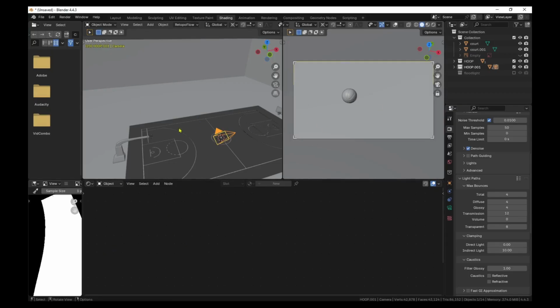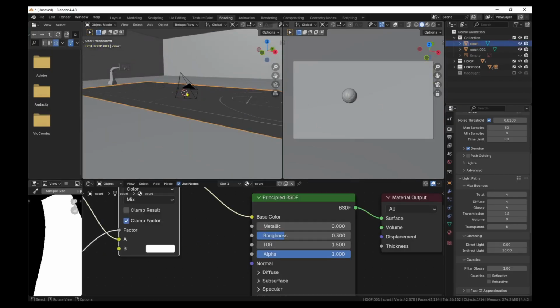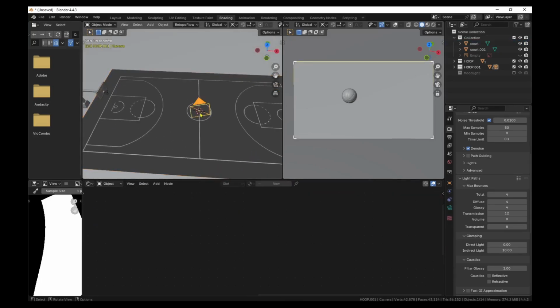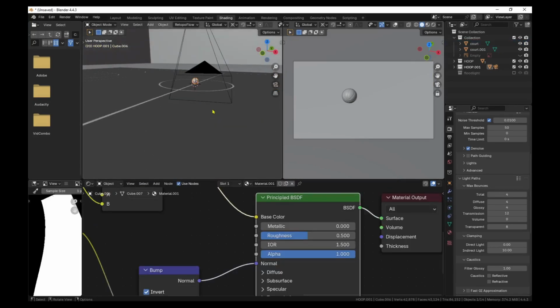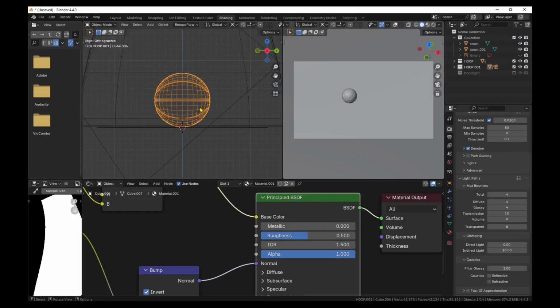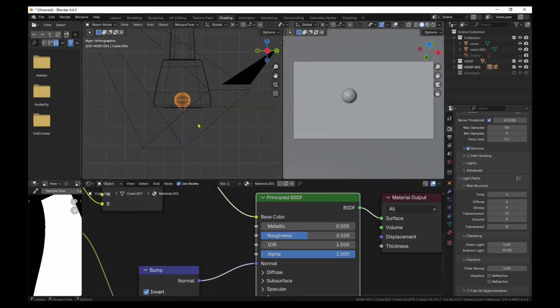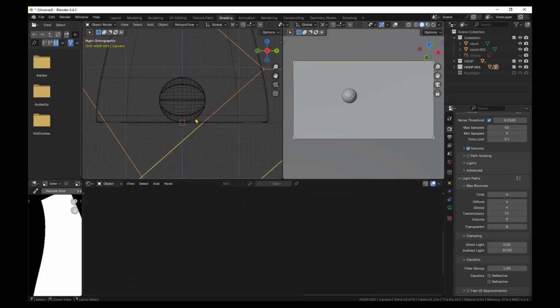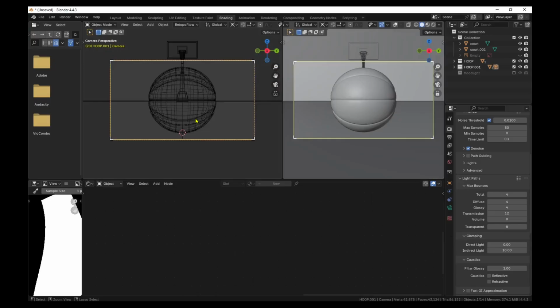So now we want to light only the ball. So let's bring our focus to the basketball. Let's select the basketball we have here. Then you can use the number pad period to move closer. And let's go to the side view, number 3 to go to your side view, and then select our camera, and then hold Alt Control and then 0 to get this scene in our camera.